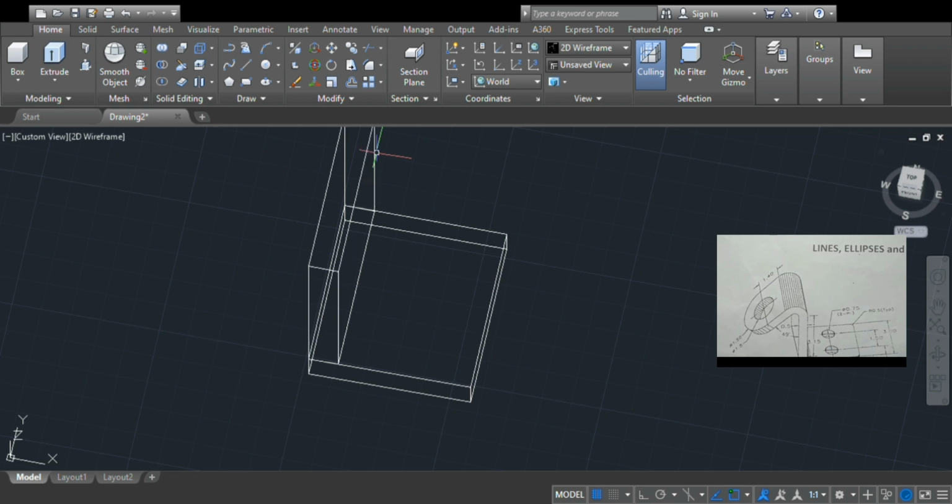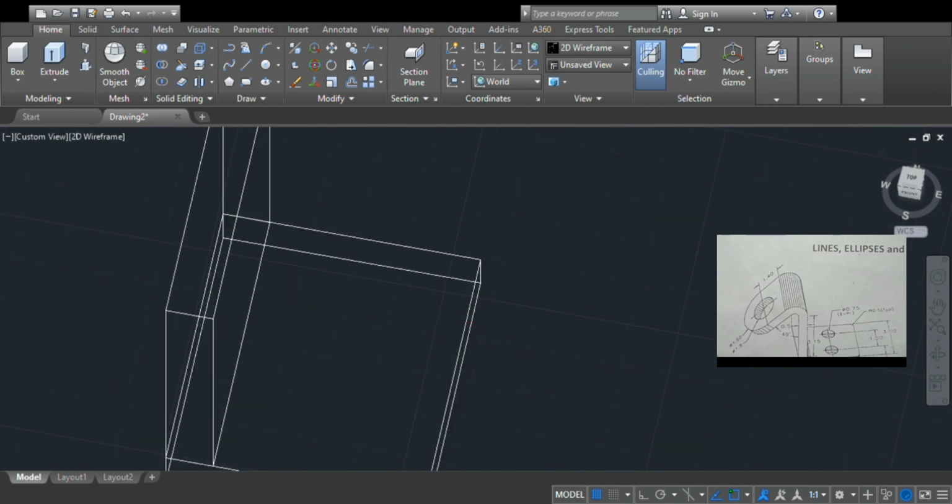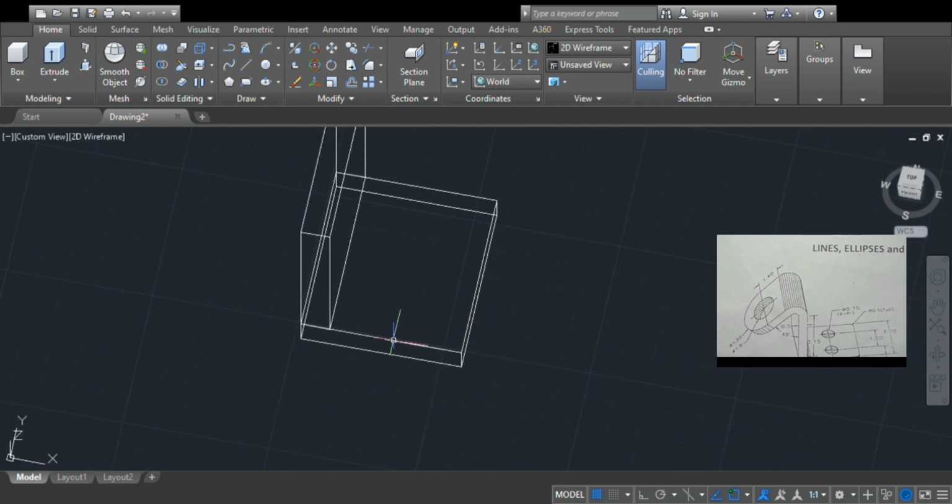Also, when creating objects, you have to know when you're dimensioning, you drag and you select. The first thing that's selected is the length of the object, and to switch to the breadth of the object, all you have to do is click the tab button. Then the height is the last thing. After clicking enter, after selecting tab for the breadth, then you select the height. For this one, I'm using 2.7 for the length of the object and 3 for the breadth, and the height was 0.5. Now the same thing I'll do for the edge.